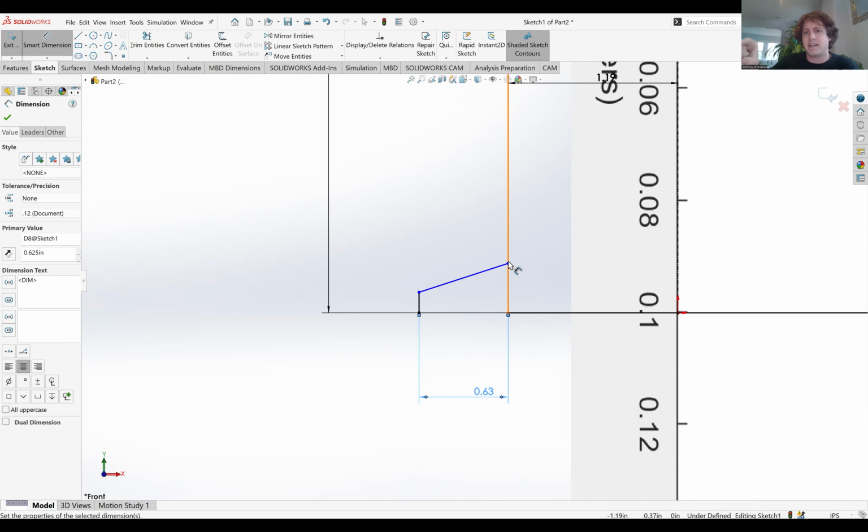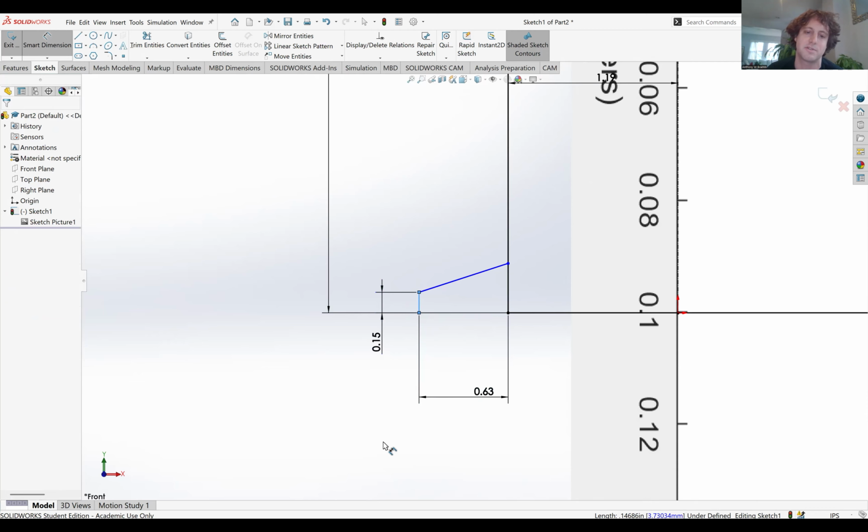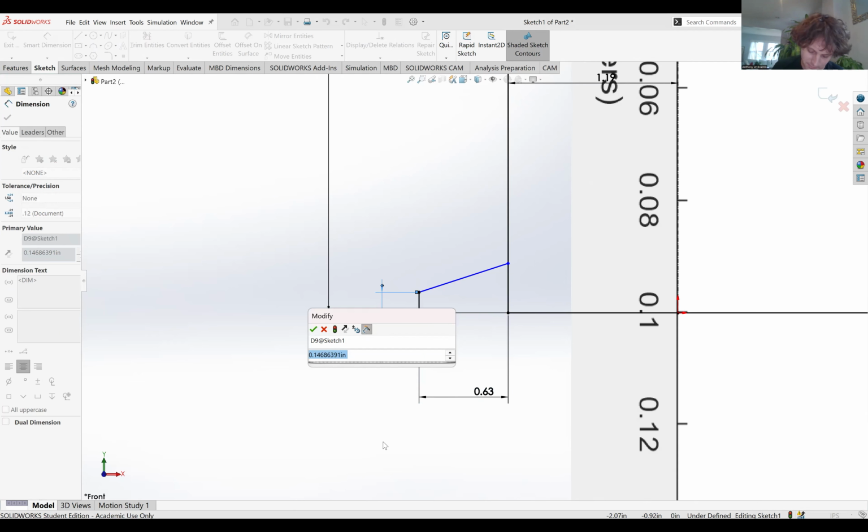One of the reasons, if you're wondering why I'm even making this lip here and why don't I just sink the nut in further: well, you could do that, and you'd position the hole from underneath to be a little bit to the right on screen. But it's hard to wedge that bolt in there quite so far, and that becomes a little bit difficult. So I want to avoid that, and the compromise is to make this small wedge out front. You could make it pretty small.